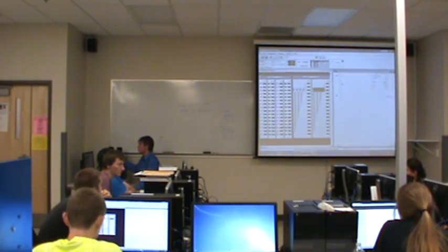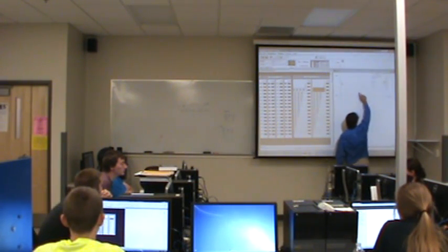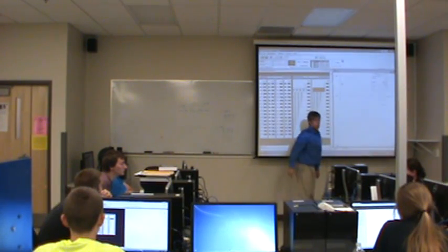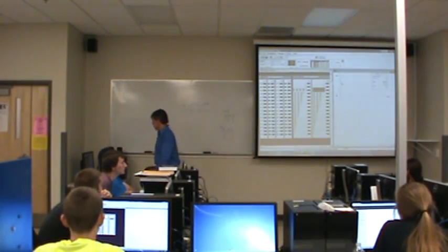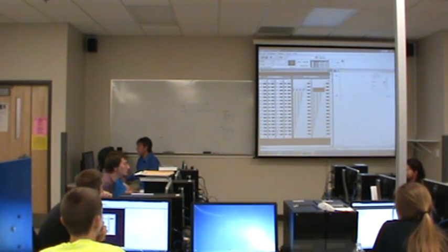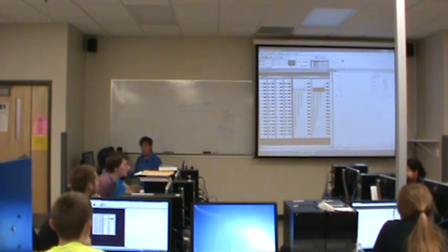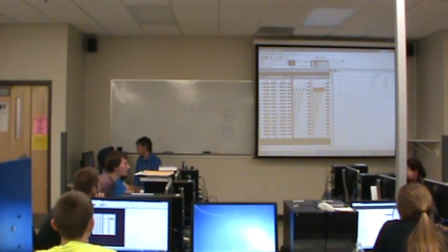Basically, every time we go through this, the instructions preceding the instruction are true, so this is going to happen every time it goes through the scan. Okay? So notice, well here, let me change this. Okay, now, if I turn on any odd input, it does not transfer that through. But if I turn on any even input, that gets copied over. See, because of the mask. Do masks make sense now? Okay, so that's what a mask is.